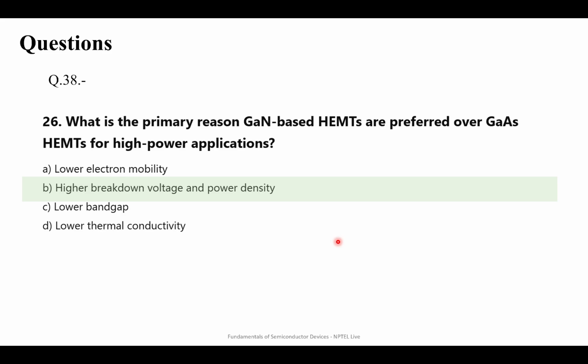That prevents it, because at that point it stops being a semiconductor, because there are conduction channels through which current, electrons, will pass through. These channels form at a certain electric field. So for gallium nitride, this electric field threshold is much higher compared to gallium arsenide.